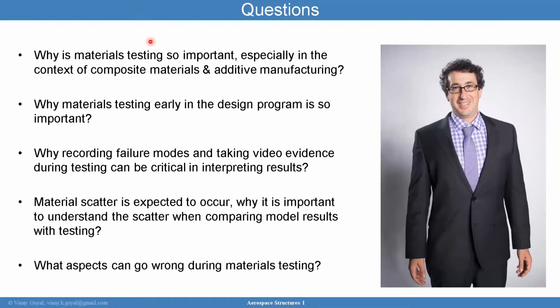I like what you said there, and I also want to make sure everybody understands that this is not just for composites and additive manufacturing. This can happen at weld ends in a metallic tank, say, or a more complicated metallic structure. Yep. Sometimes you get large grain sizes in these metals that could yield low fracture toughness, low yield behavior, and behave more brittle.